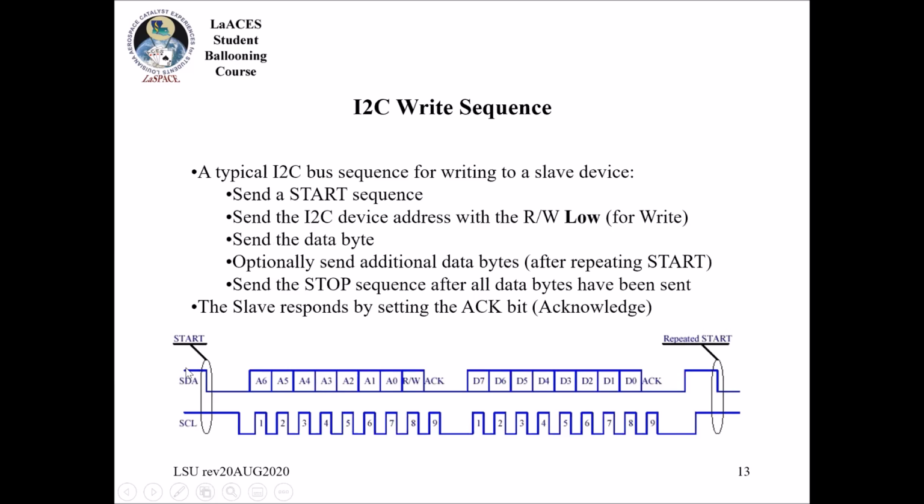Okay, so let's look at this down here because it's a little easier. Remember, these are 2 wires going between the 2 devices. On the data line, the master pulls it down. The first thing it needs to do is send an address to all of the things that are out there, so that particular device can wake up and say, oh, I'm here. So it starts, sends all of the bits, and then we have this read/write bit because it needs to say, hey, number 86, I want to write something to you, or, hey, number 86, I want to read some of your data.